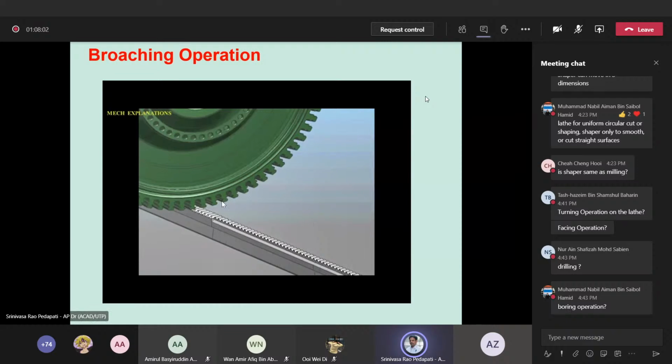So this is again animation. You can also have a linear broach, something like this. What is shown in the previous application is a circular broach to make circular objects, circular holes and grooves that are required. You can also have external cutting with a straight broach, like gear cutting or gear wheel broaching, etc. This is called gear broaching.